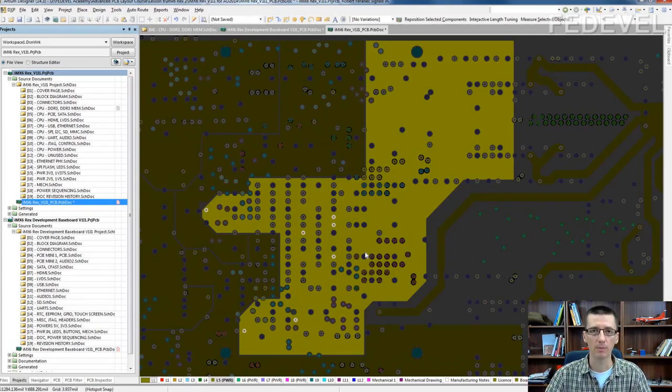You remember when we were speaking about layer ordering, I mentioned that if you have a ground plane and a power plane, then together they can create some kind of capacitor which can help you filter noise on the power plane.